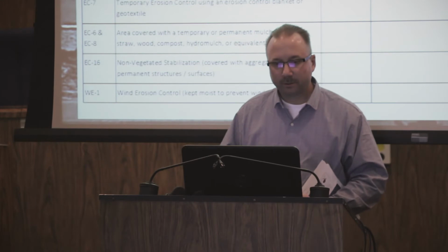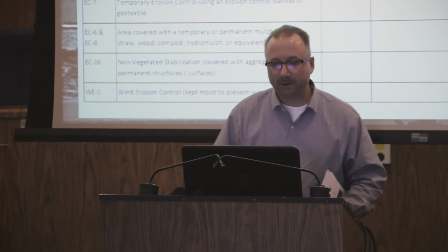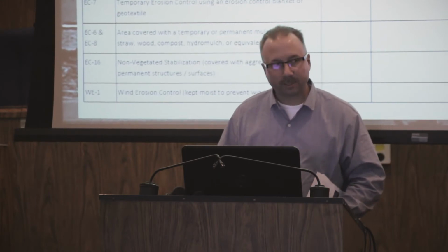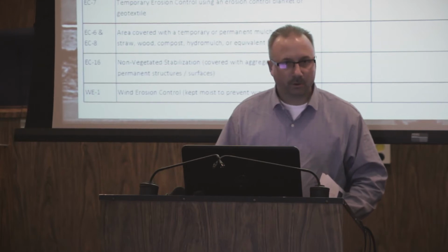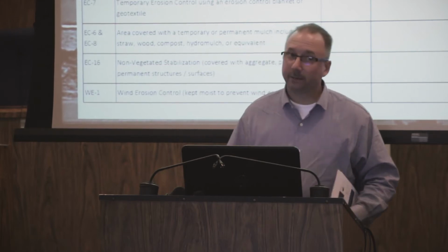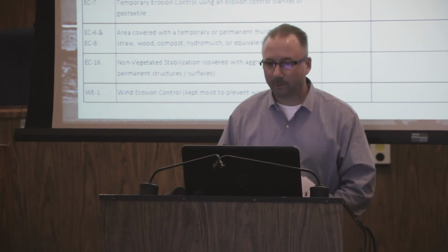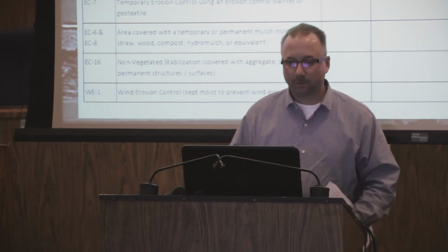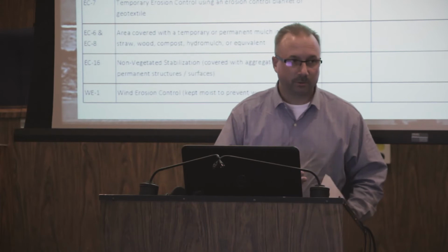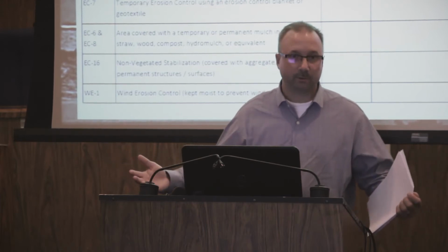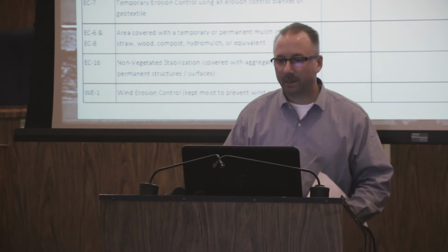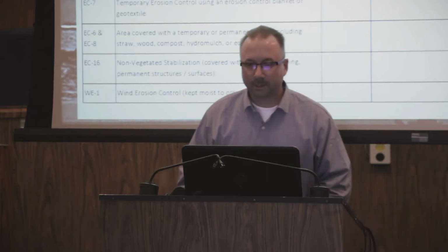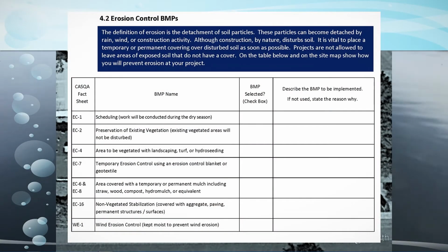Projects are not allowed to leave areas of exposed soil that do not have a cover. So no longer is it allowed by city ordinance and also by the state water board's regulations to leave a site with just dirt, exposed dirt that was disturbed during construction. It's got to be stabilized in one way or another. On the table below and on the site map, show how you will prevent erosion at your project. And so we're going to walk through some of these.